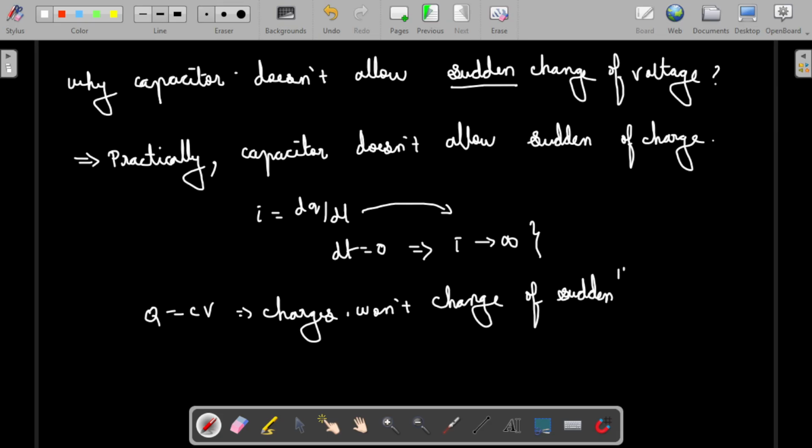So that is one important thing, guys. Whenever there is a sudden change happening, the capacitors will not allow it. The plates connected together can transfer charges to each other, but the charges of these plates cannot flow elsewhere. Between the two plates they can exchange charge, but that charge cannot go anywhere. So the principle of charge conservation is that charge can neither be created nor destroyed. We apply charge conservation to the plates of capacitors connected to each other. That will help to solve a few problems.